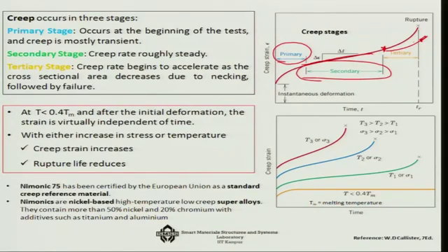So, that actually goes towards the failure. Now, at temperatures less than 0.4 of the melting point temperature, generally after the initial deformation, the strain is virtually independent of time. But with the increase in stress or temperature, the creep strain increases and the rupture life decreases rapidly.